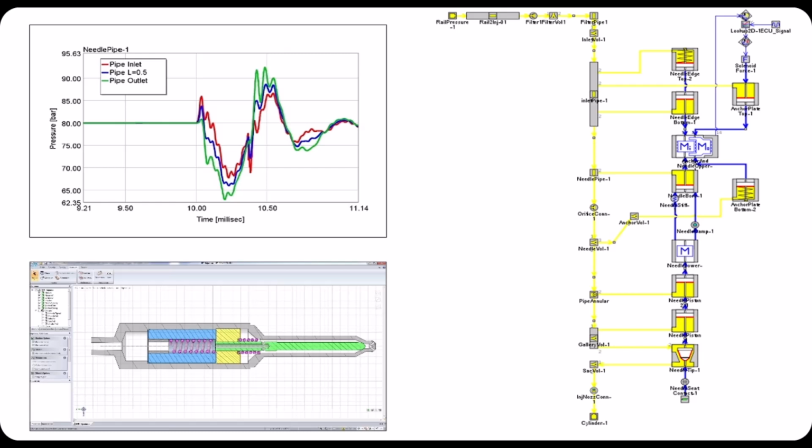And let me say, a GDI injector must produce a very precise and finely atomized spray because the fuel is injected directly into the combustion chamber. Okay? Therefore, the design of the nozzle and the angle of the spray holes play a critical role in combustion quality.